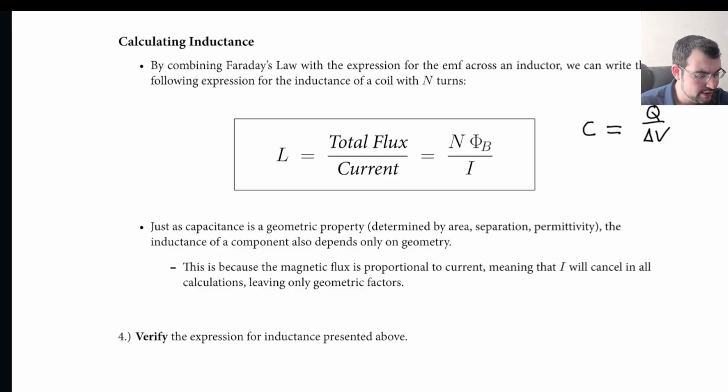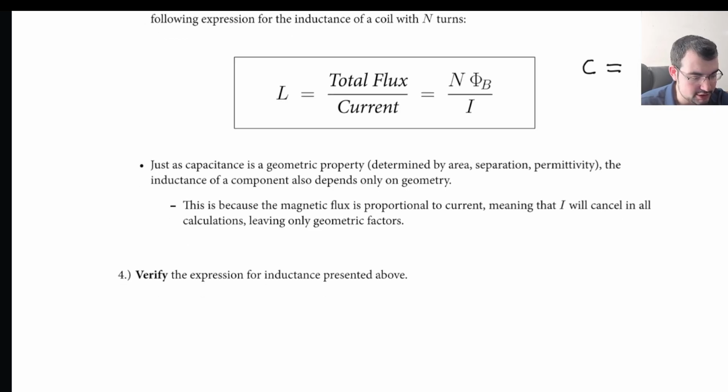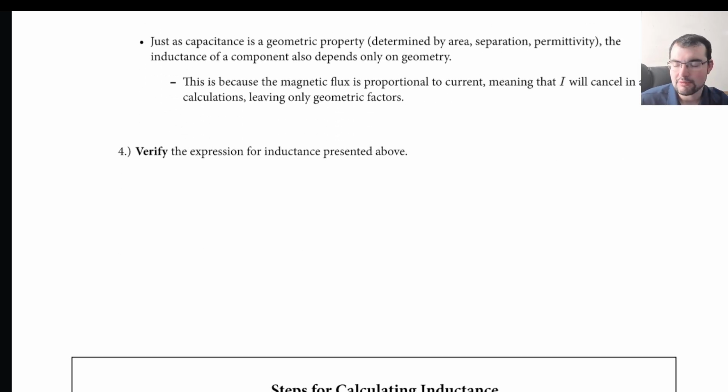First, let's verify that this is the correct expression for L, consistent with our definition. We said the induced EMF through a coil is negative to fight the change, depends on the rate of change of current, and L is a proportionality constant. But that's not the first time we encountered induced EMF. That's just Faraday's law.